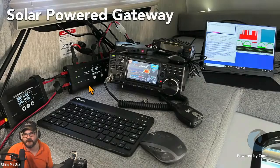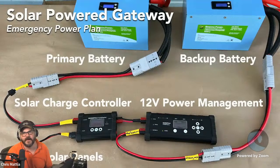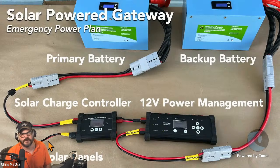This is what we set up when we were out in the field, as the solar powered gateway. Instead of having a power generator out there, we used battery power, and we were recharging the batteries off of the solar. It ended up looking something like this, where we had our primary battery, a 60 amp hour battery, connected into the solar charge controller. This bottom port here is a link out to the solar panels.